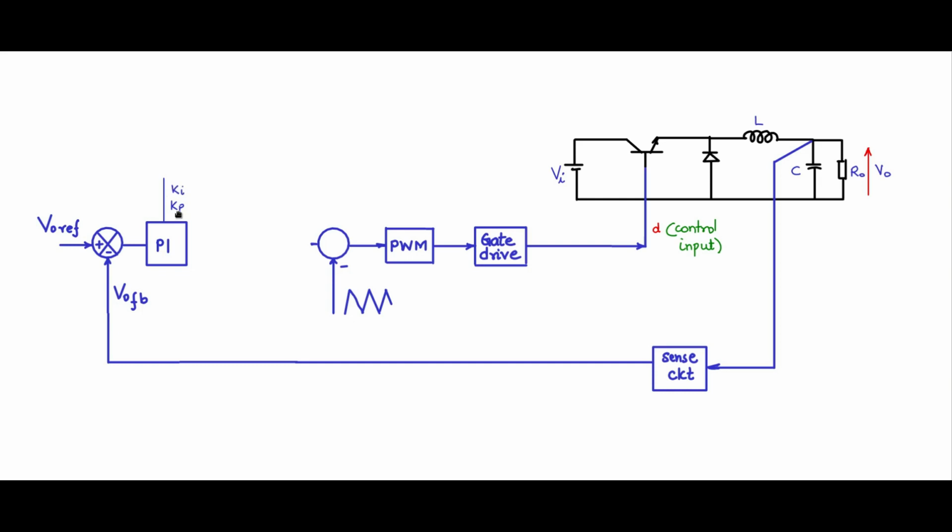After that, increase Kp from 0 gradually to pull up the transient performance. So this is the error, and the output of this is connected to another summer, and that is where we attach the feed forward term. That feed forward term is the steady state duty cycle, the uppercase D, which will decide the nominal operating point or the steady state operating point.